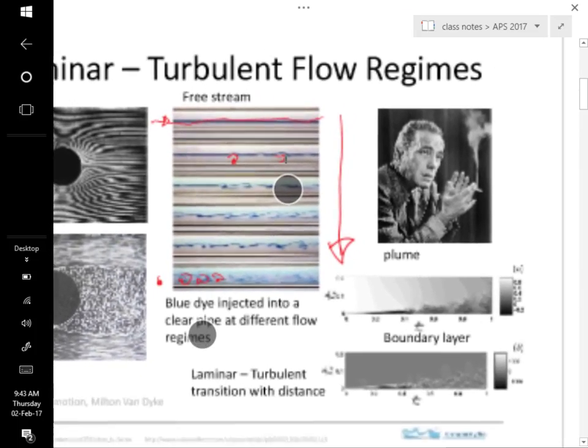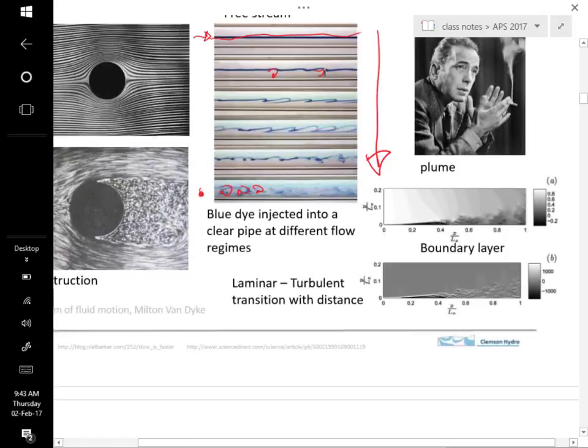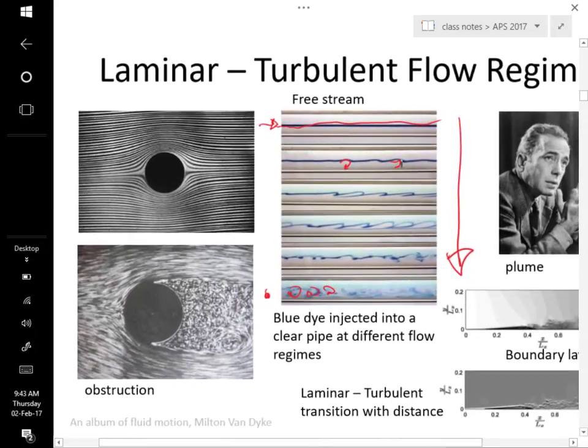And so here's the flow past a stationary object, and then here's the wake. And this is the flow past the circular obstruction, and this is the condition where you could get Kármán vortices, and you kind of see this vortex like that, but this is a much higher Reynolds number than what we saw, and so you can see that the pattern in here is much more complicated.